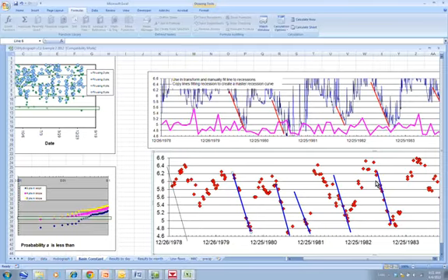And we saw in the previous video and in the notes that go with this analysis that during a base flow recession, we expect that the flow in the stream will conform to a negative exponential function of time, with A being the coefficient up in the exponent. So one thing we can do is make these fits, and Excel allows you just to drag these over, bring them together here, just so we can do a comparison.